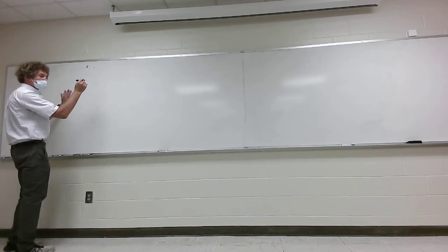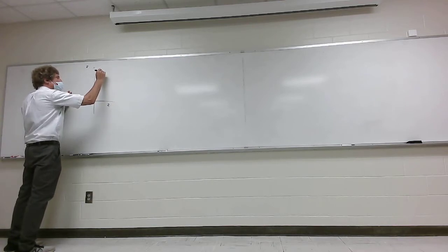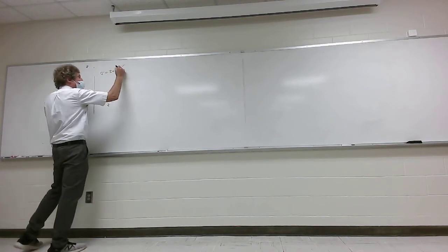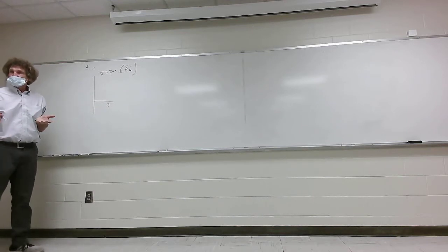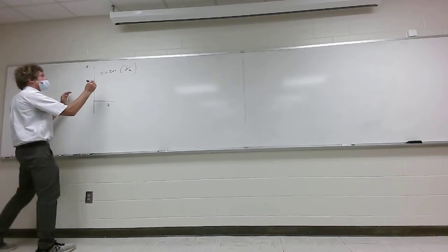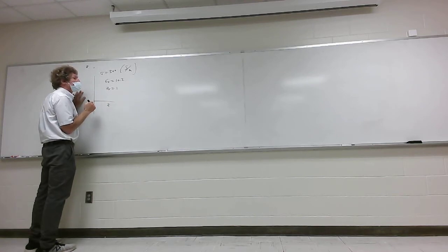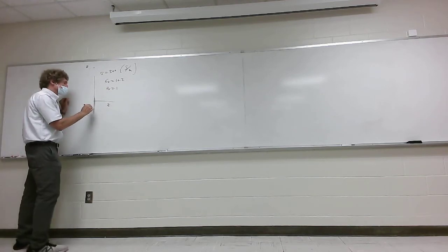I'm trying to find it. 622, did you say? A semi-infinite slab exists for z greater than 0 with sigma equal 300 S/m. That's Siemens per meter. I like to put 1 over ohm meters because you're used to ohms. Epsilon r equals 10.2 and mu r equals 1. And then at the surface z equals 0, what is the E field?